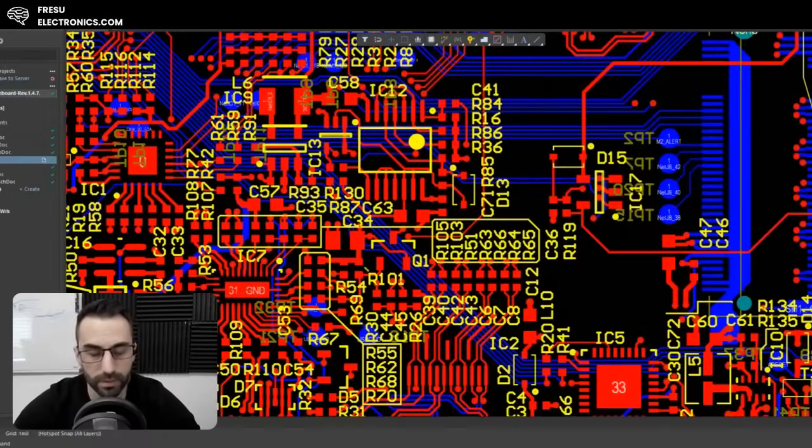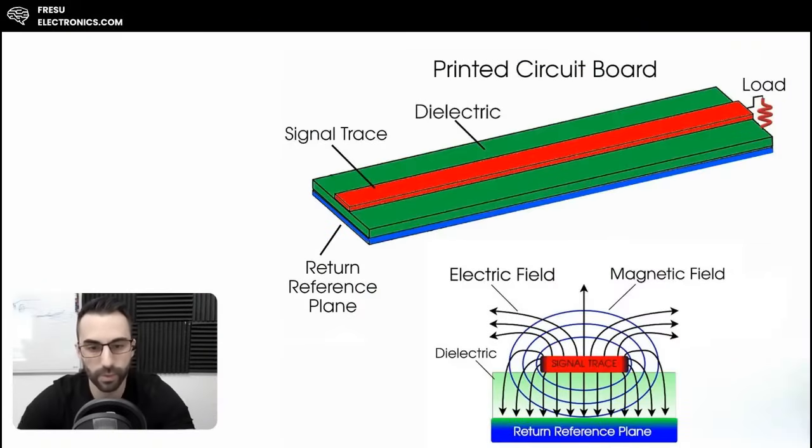One of the most important concepts in designing printed circuit boards for low electromagnetic interference, or simply EMI, is understanding electromagnetic fields, specifically how to contain and control them. EMI is fundamentally about field containment, and it's about controlling where these fields need to be strong and where they need to be weakened. And when we discuss fields, we are referring to both electric and magnetic fields.